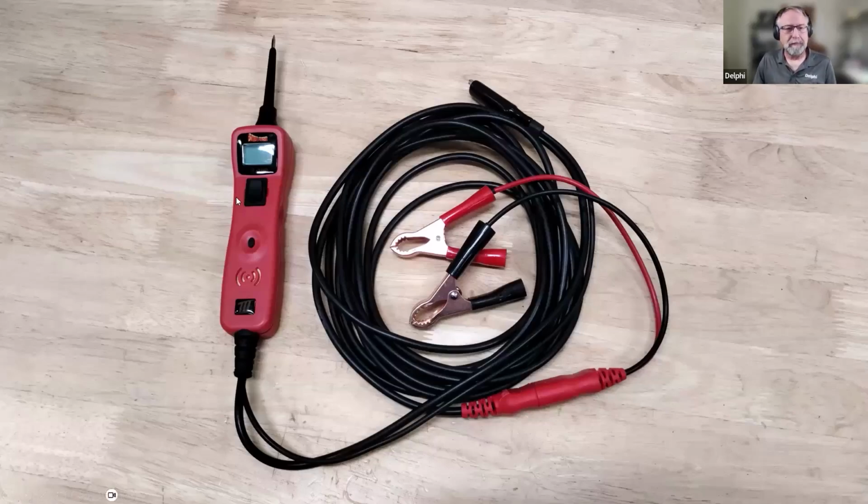And guess what? Power probes in my world are one of the best things that's ever been invented. And the reason I say this is because it is always taking measurements with the battery itself as the point of reference for all the voltage measurements. That is the best attribute of the power probe. All of your voltage measurements are being made with the battery itself as the point of reference. That's huge, absolutely huge.